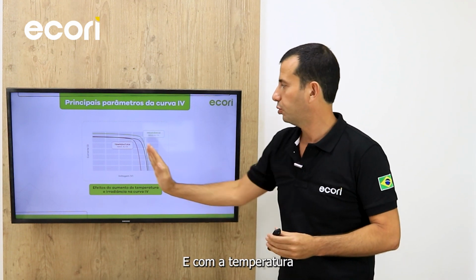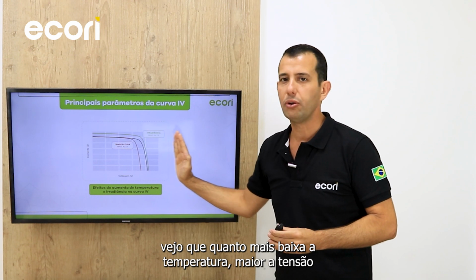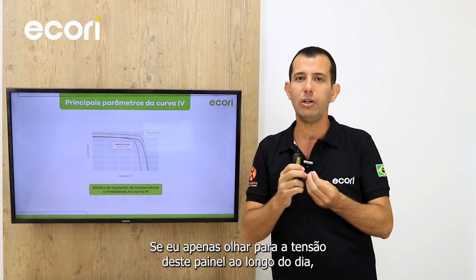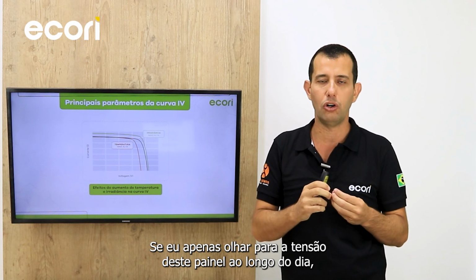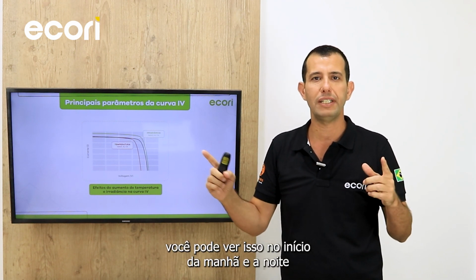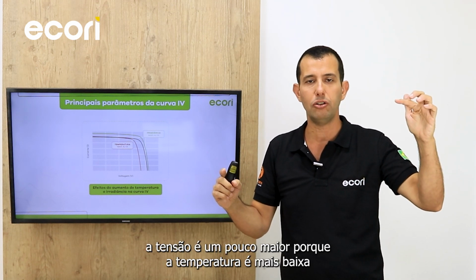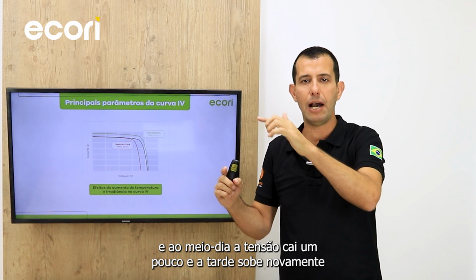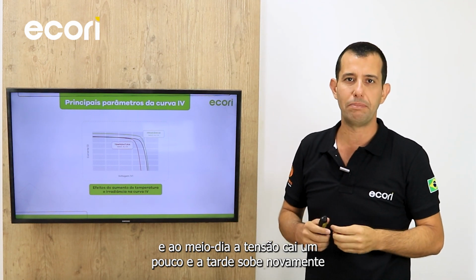And with temperature, I see that the lower the temperature, the higher the voltage. If I would only look at the voltage of a panel throughout the day, you could see that in the early morning and in the evening the voltage is a bit higher because the temperature is lower, and in the midday the voltage goes a bit down and in the afternoon goes up again.